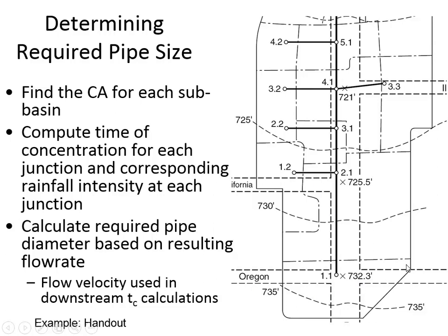And what they've also done is they have, with these break lines here, identified where the water is flowing to. These circles represent inlets to the system. And so any rainfall that is in this area, in these boundaries, is going to flow to inlet 1-1. The water that gets into inlet 1-2 is in this area. All right. Inlet 2.1 is everything from this dashed line over to the boundary, over here, down, sideways.